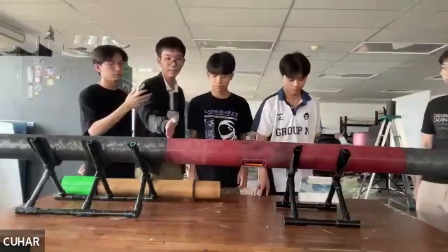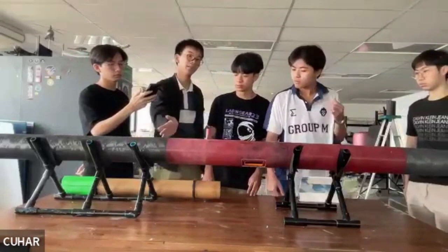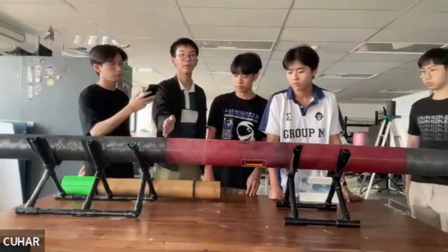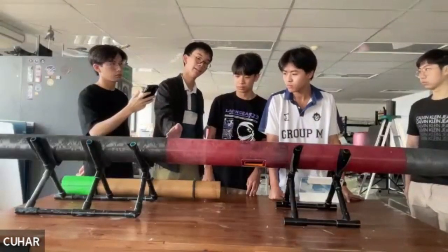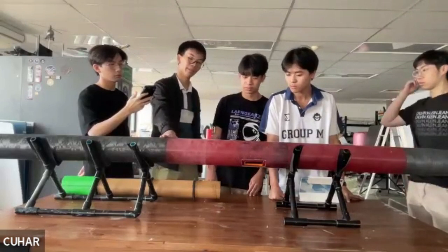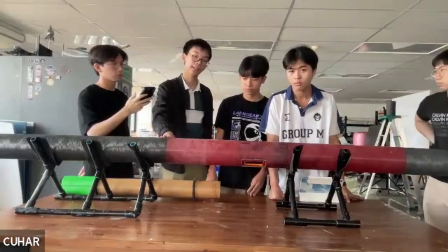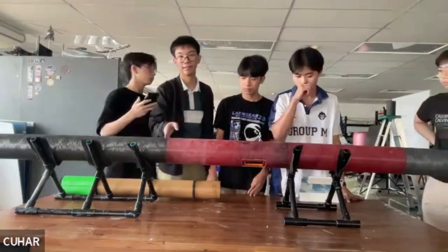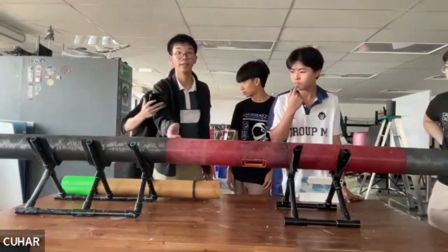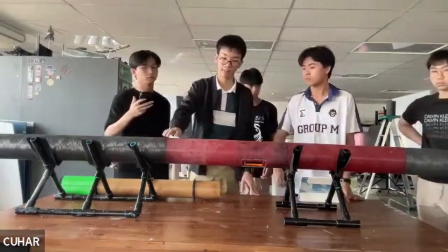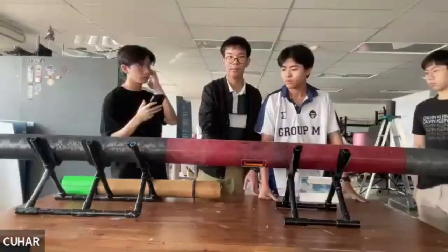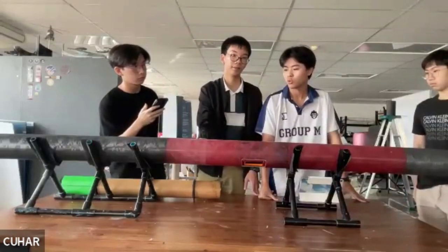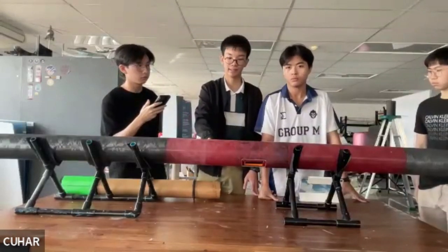Okay, so basically inside here will be another bulkhead just for safety measures. So if there's more force coming through from the booster section on the top, the forces will come through this bulkhead. It's a flat disc that helps receive the load from the thrusters. And this hollow part you see is where we're going to put our drogue parachute. This is where we're going to deploy first.